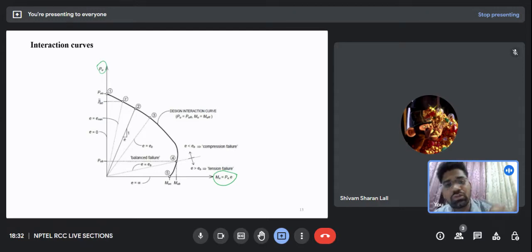So this is also an important point. In any competition exam, they will ask you what is the eccentricity for this P and this M, and they will give you the slope values. You will get confused, but this is as simple as that. You can see it here. Now another important point. First point was what? The slope. Slope will give me eccentricity.